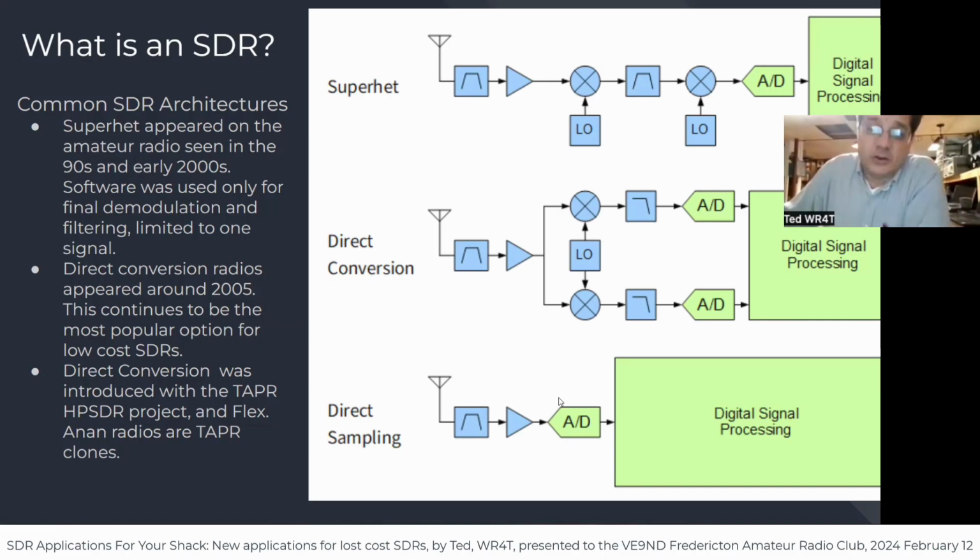And just to give you an example, Elecraft just released their first direct sampling radio, the K4, and in order for it to equal the specifications of their older K3, they actually have an analog receiver board as an option you can add to the radio, and it will operate with both the direct sampling receivers and the analog receiver. And of course, the transmit is always digital in either case.